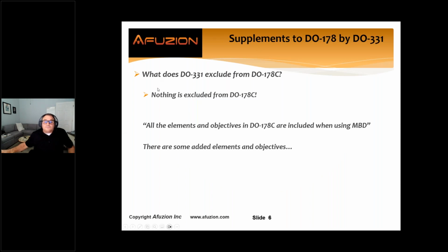DO331 excludes nothing from DO178. All the elements and the objectives that are contained within DO178C are also included if your project is going to use model-based development. So you don't get to save any steps along the way. However, there are some added elements and some added objectives that you need to cover throughout your design.